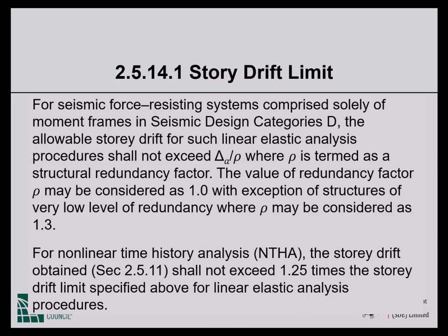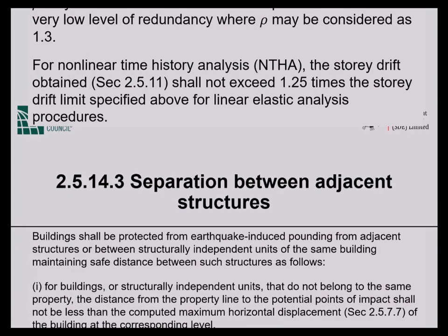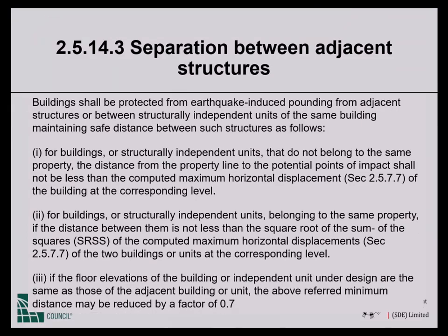So if you base your interstory drifts on nonlinear time history analysis, then the drift limits are relaxed by 25%, which is actually very modest in US practice. The relaxation is quite often quite a bit higher than that. Okay, so that is drift check.